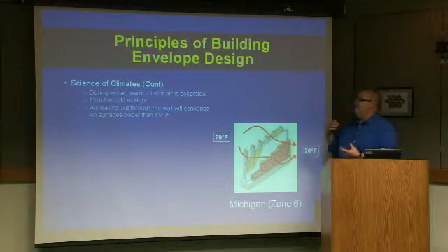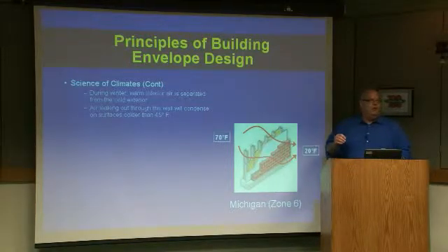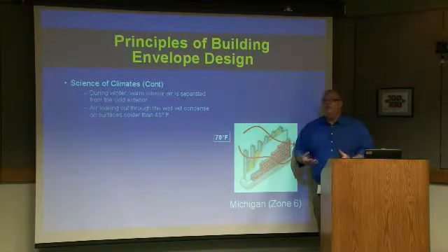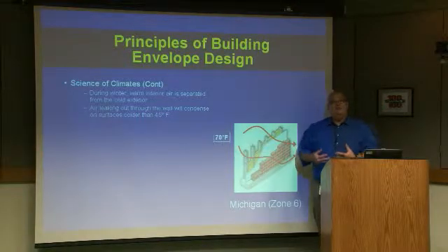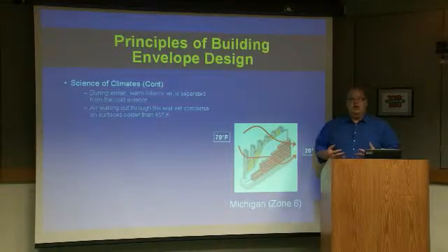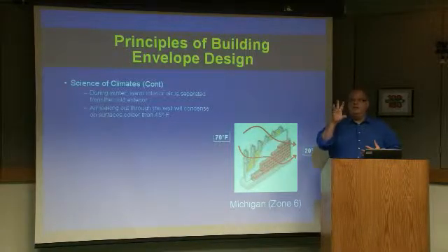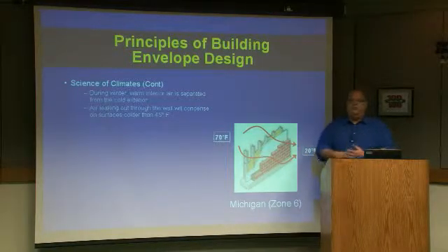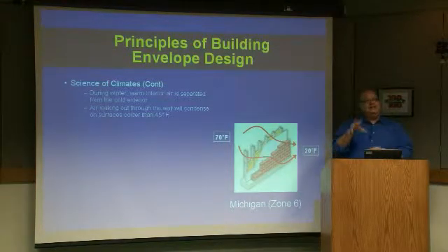We typically see a lot more mold problems in the south though, because mold only goes aerosol when it's above a certain moisture level. When people have a reaction to mold, it's most closely described as an allergic reaction. That is not medically true. It is not medically an allergic reaction, but for most of us, that's the easiest way to think about it. You're going to react when the mold goes aerosol, when it starts putting its spores out into the air, which is when it's above 17% moisture content, when temperatures are between 41 and 104.